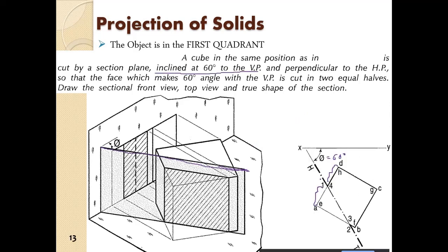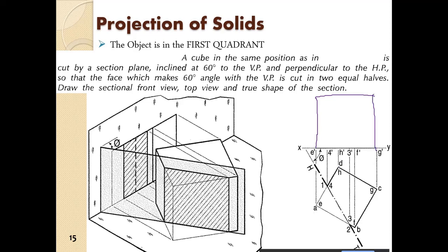So first step, second step. Then we project it upwards. First of all, we project it up and we draw the cube. So this line will be hidden, a dotted line. So DH is this edge, so it will be a dotted line. FB will be here. And then we project this plane.